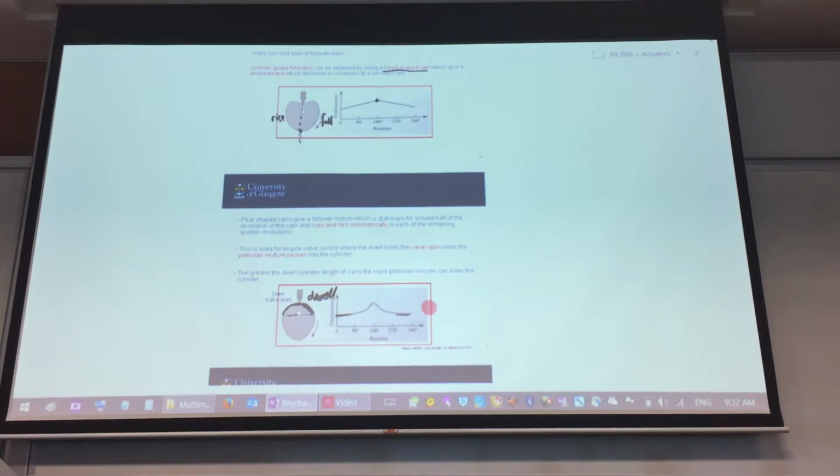Why are all these things necessary? That's because if you have sight of your acceleration profile, it would tell you whether the cam that you have designed is giving you a smooth response. How do I relate that? For your follower that's following your cam profile, had your cam profile not been the right kind of profile, such that there's an abrupt change of acceleration, you can imagine that your follower is going to knock on your cam.